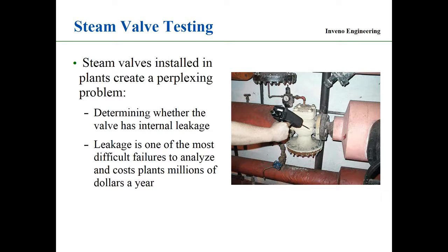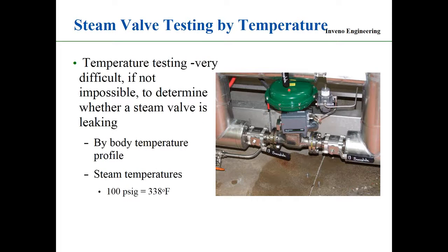So it comes down to: how do we test valves for internal leakage? Going up and saying, geez, the valve is hot on one side, hot on the other side, doesn't really work. Because we talk about energy today, with 100 psi coming into the inlet of the valve, it's going to be 338 degrees Fahrenheit.